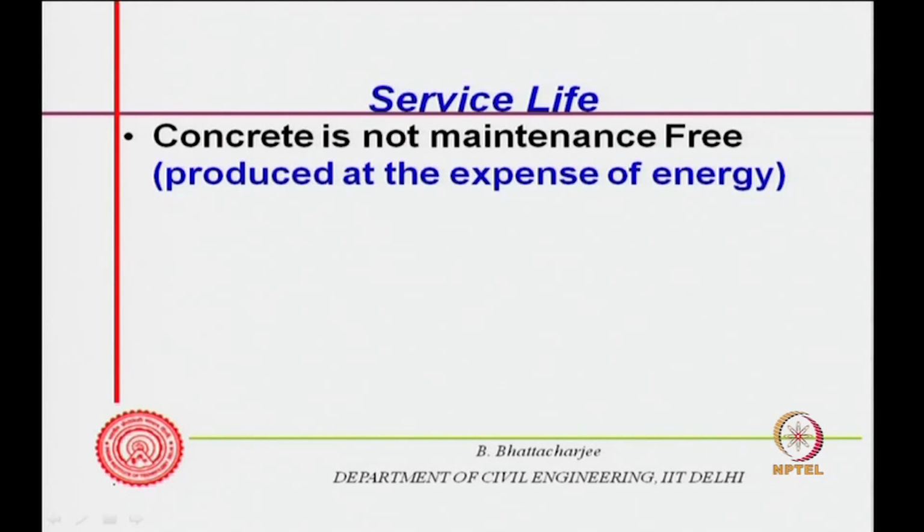Aggregates, if they are fine powder, like after abrasion, a natural process, fine sand, very fine sand, large sizes also have got reduced. So, by fracture, they have dissipated all possible energy and come to the finest size. That is actually a stable material. Rocks may not be stable all the time, compared to, of course, fine powder of the same material, because they can still break into new surfaces and dissipate some more fracture energy and create new surfaces. So, in some of the aggregates, some energy might be locked in, but not necessarily. It is mainly the cement paste and cement hydrate system that has somewhat higher chemical potential, and would actually tend to dissipate that given a conducive condition.